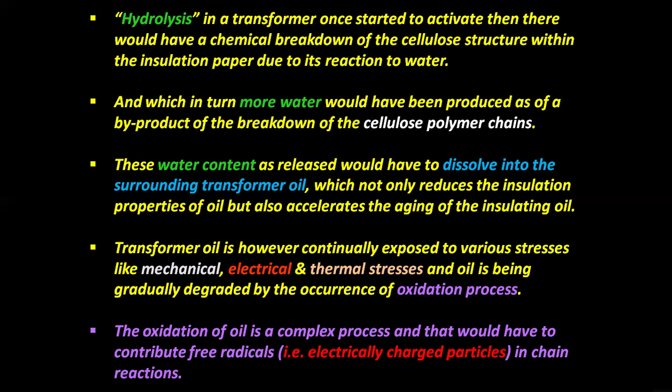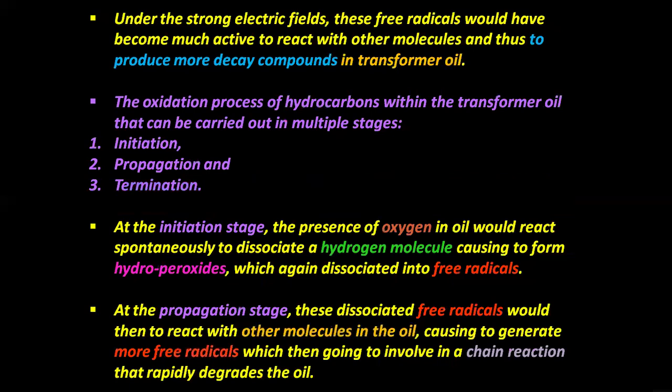The oxidation of oil is a complex process that contributes free radicals, that is, electrically charged particles in chain reactions. Under strong electric fields, these free radicals become much more active to react with other molecules and thus produce more decay compounds in transformer oil.